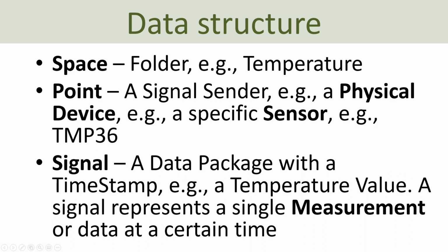And finally you have signals. That's the actual measurements. So you store the signals within a point, and then you locate the point in a space, and the spaces can have a hierarchical structure, where you can have the main space, and you can have a subspace below that space, etc. Just like you have folders on your computer. And then you store these points inside these spaces, and then finally you have these signals.